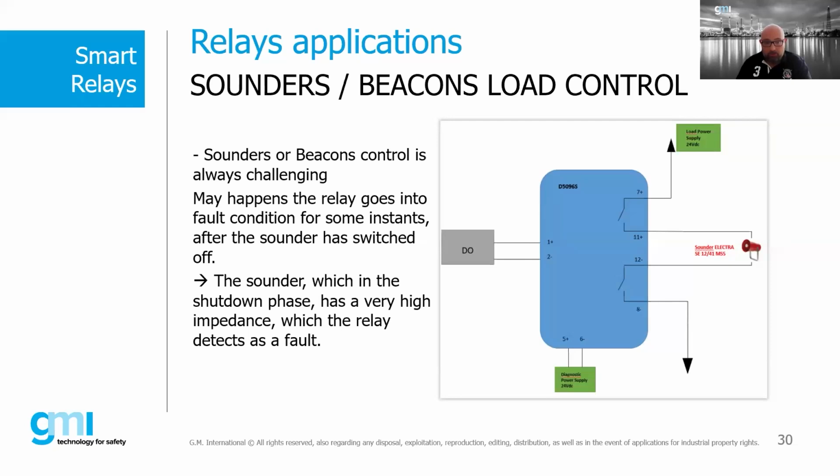These problems often occur with this type of field devices, and to overcome them, it's necessary to insert a resistor, a so-called end-of-line resistor, in parallel to the device itself, which allows us to bring the impedance values of the field device within the diagnostic range of the relay.